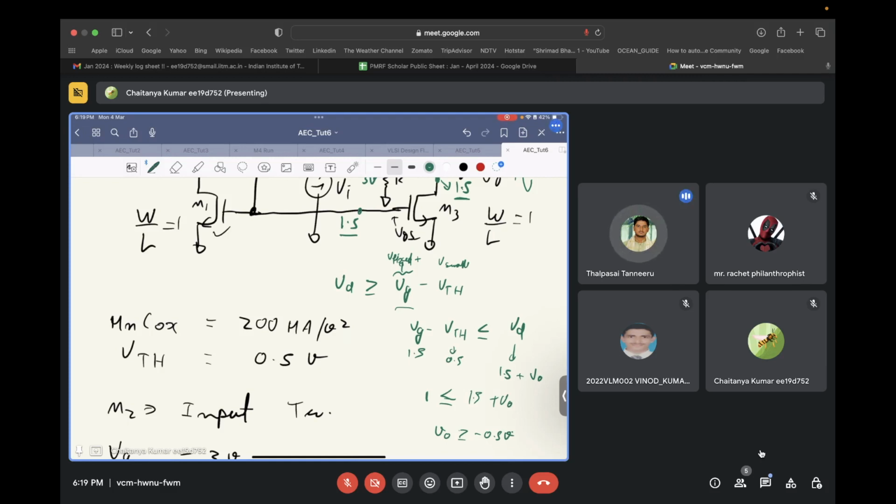Sir, at the time, if we don't consider the drain voltage, right? Sorry, I didn't get it. No, sir, while doing the assignment I also get confused, while we are calculating the peak voltage. Sir, here in this case, the drain voltage is varying, so we consider the drain voltage. We ignore only the fixed DC voltage. We don't consider the small signal voltage, small VG, right? Yeah, because small VG is zero in this case. Oh yes, correct. Got it.